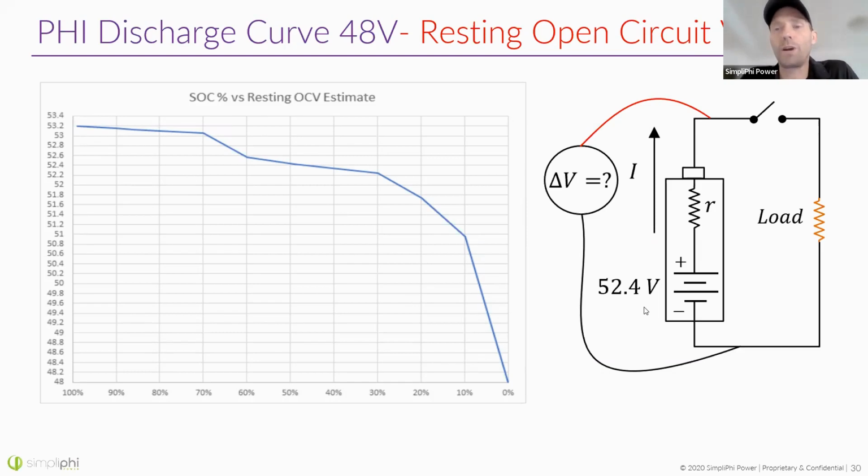So Russell, a good rule of thumb is for our lithium batteries, as long as the breaker is switched off, they discharge at about 1% per month. So they have a pretty long shelf life. It's just that we have to ship them at a 30% state of charge. And so at 1% per month, we recommend topping them up every 6 months. But batteries can sit a lot longer if they're starting at higher states of charge.